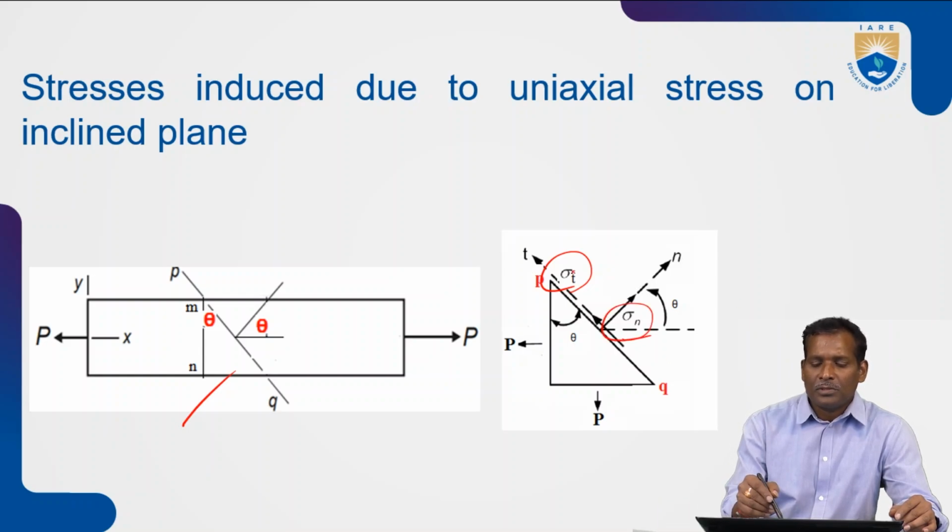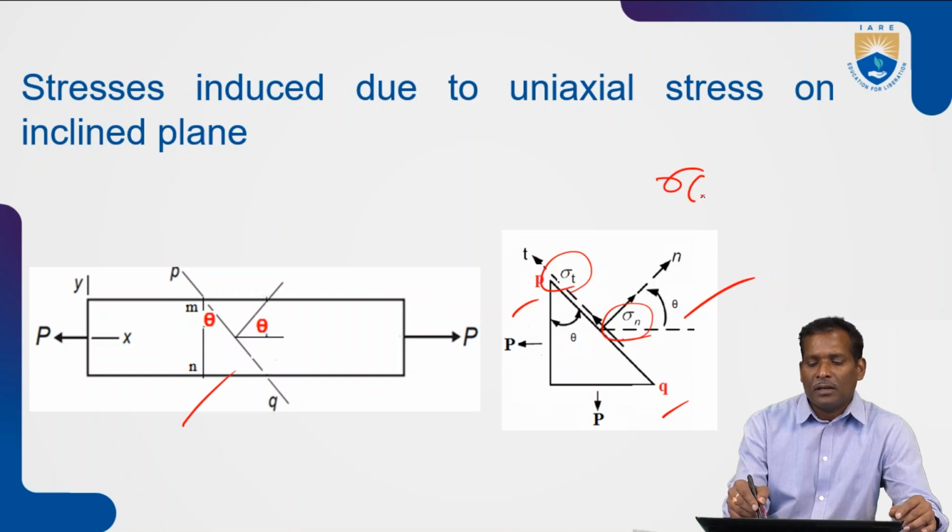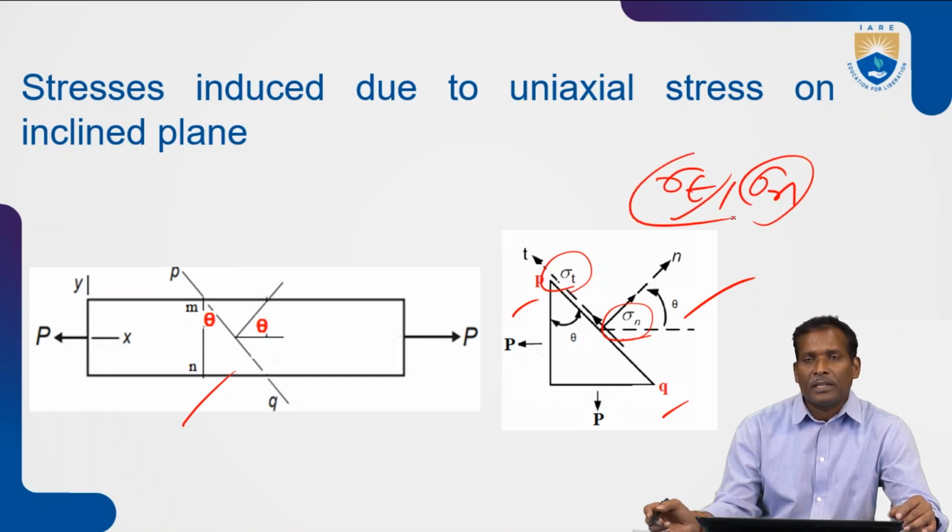The force is resolved into two components on this PQ plane with the angle theta, so you can calculate the normal stress and tangential stress on this particular plane.